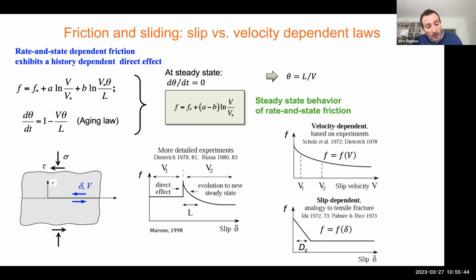Now, one behavior these analog materials display is that they are rate dependent. So if you use an effective linear elastic behavior, you need to account for the high strain rate properties. What we do is take a dynamic value of Young's and shear modulus, and we use those to obtain stresses from strain.